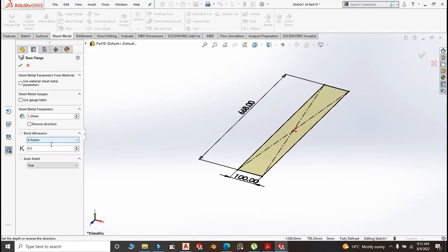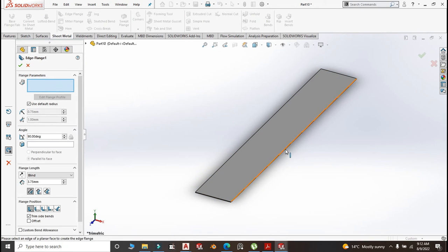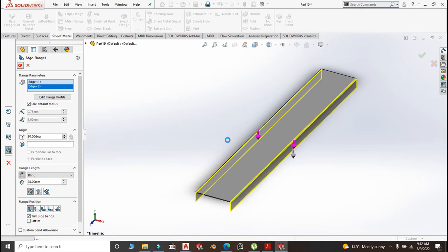This should be 1.5. You know, this is carrying weight. That channel should be 1.5mm thick, right? Create an edge flange here. Remember our edge flange of the undershelf is 30mm. Do this 28mm. That's good.